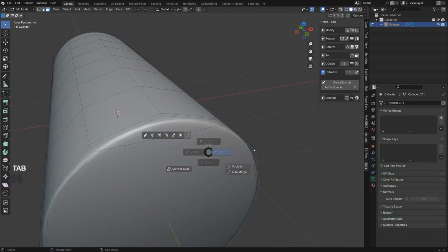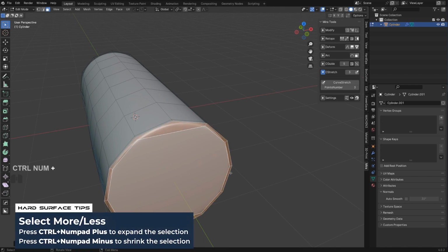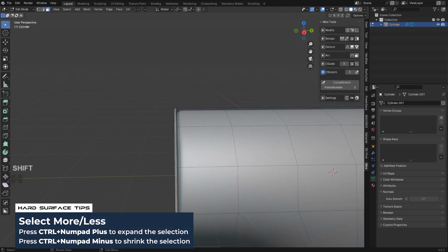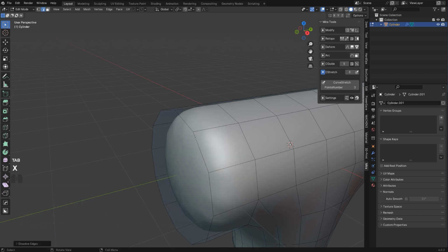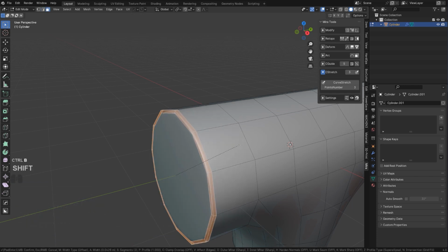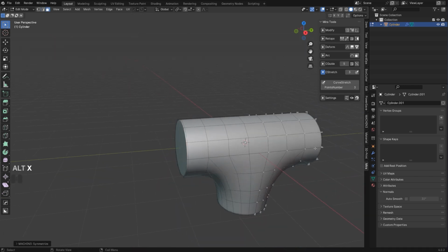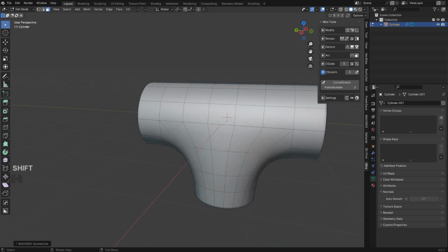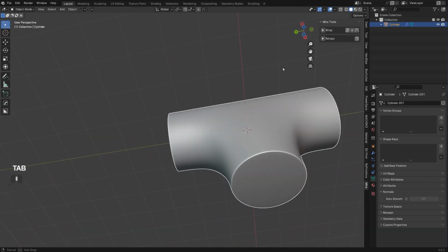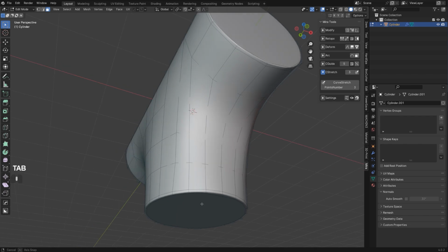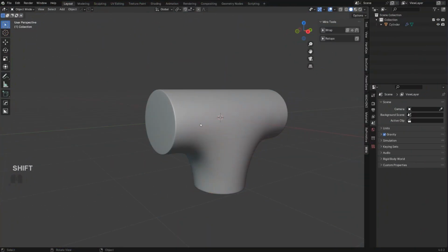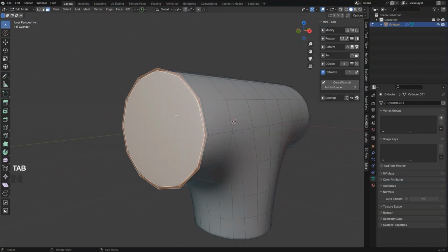There's a disaster in here, so what we're gonna do is simply do that and remove this edge here. Grab this one and bevel this one more time. Alt X to the other side. And we cooking with fire. Here at the bottom, everything is good. Awesome. Now for the elements here on the side, we're gonna need more dense geos.